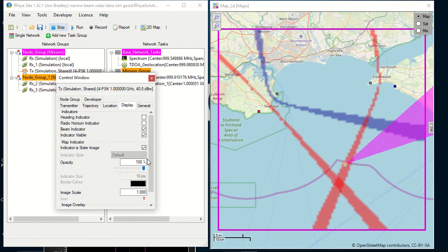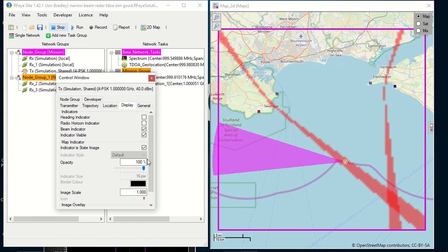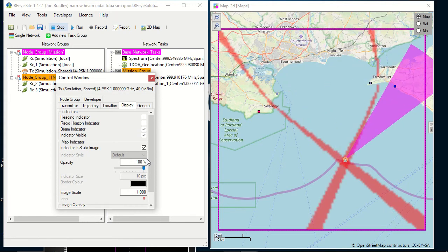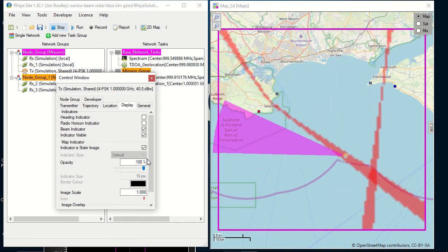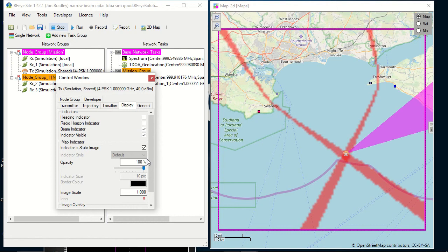So with appropriate geometry and a clever bit of technical jiggery pokery, even with just 4 omnidirectional receivers, 2 sets of 2, we're able to perform this isochrone. Overlaying the isochrones, here we go, is actually giving us the geolocation of a narrow beamed transmitter on a flying object, an aircraft in this case. So it's a cool way of doing this in a very simple and very cost-effective methodology without having to resort to the much more expensive AOA systems. Interesting technology from CRFS. Thanks.